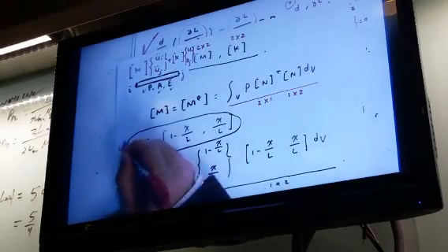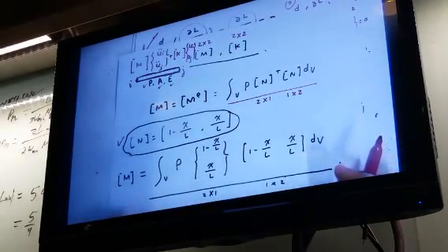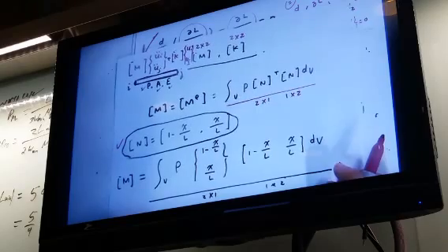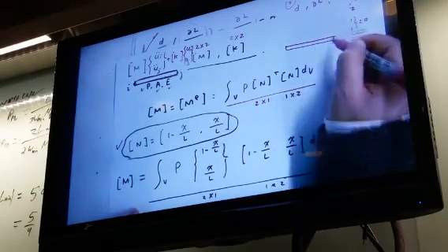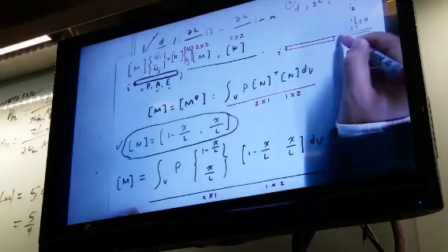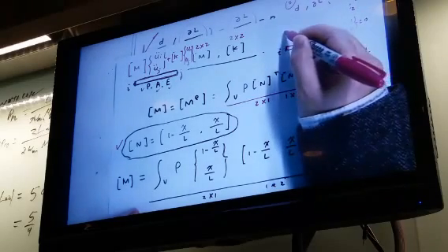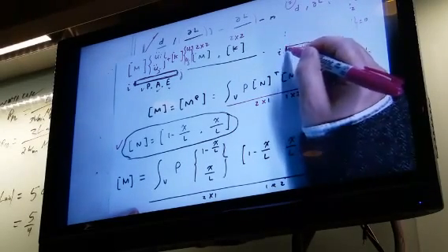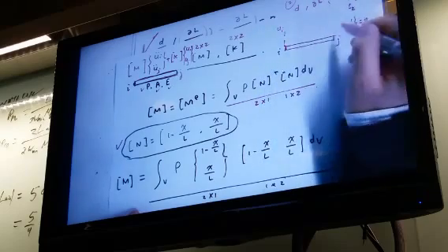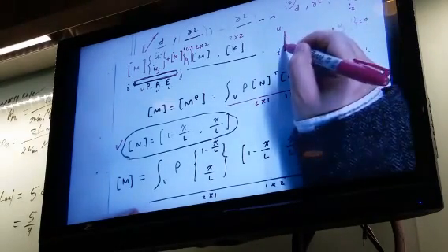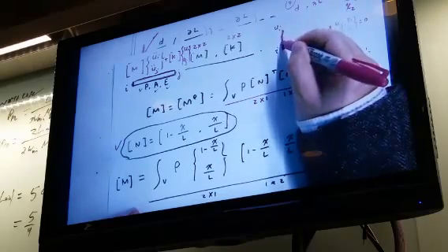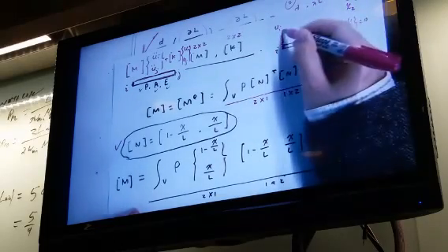So in the stiffness matrix method, we define N already. N is the so-called shape function. The shape function is also an interpolation function. Basically, this is i, this is j. If the displacement here is ui, the displacement here is uj. This is not a direction, this is a magnitude. Okay, ui that much, uj this much.